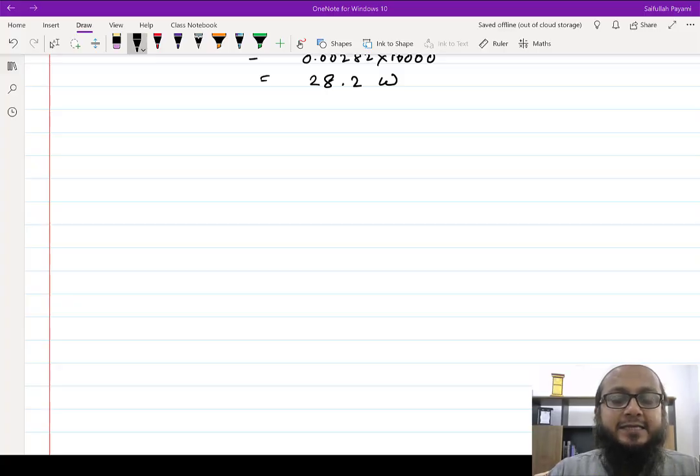obviously that means they have been defined for its rated voltage and apparent power. Similarly, for the other machine, they have given you the per unit values, and the voltage rating and power rating are different there. So obviously the per unit quantities of those parameters would be different. Now if you are using two or three machines with per unit quantities defined for different base values, then obviously that won't form a common circuit.